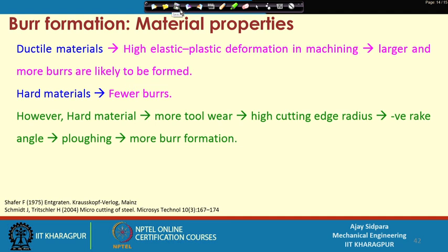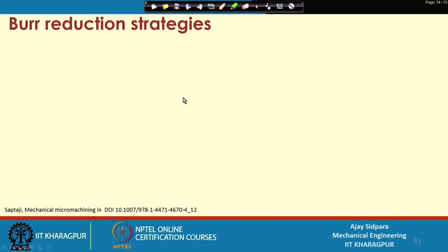So, from this slide we can understand that whether you cut a ductile material or a hard material, you cannot avoid burr formation. The only thing is to see how, by changing the different parameter settings, we can reduce the burr formation, but there is no way you can eliminate it completely. Now, let us see the burr formation strategies.